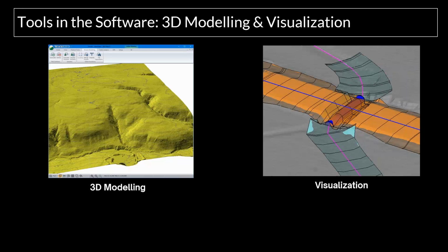So before I pass it to Matt, four tools inside of Roadhenge are also really worth noting when you're doing culvert projects. The first is the 3D window. I know there's some folks and users of ours that don't look at it too much. I encourage you for culverts, open it up, leverage it. 3D modeling in both the terrain and location module is really useful, as is the 3D visualization, especially what you're getting from the corridor surfaces in those major culvert projects.